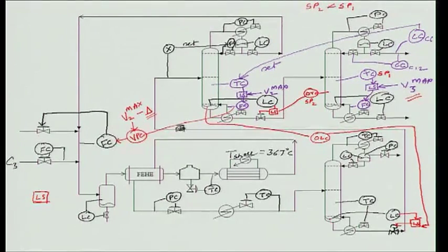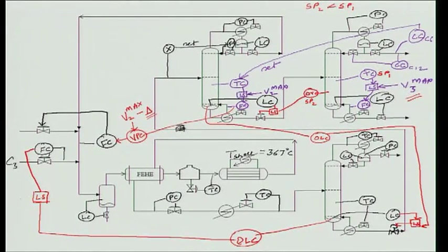What that does is override level controller, that basically, and this is the operator input set point, flow set point, flow of the propylene set point. Okay. Now that I have drawn it, let me just explain it.